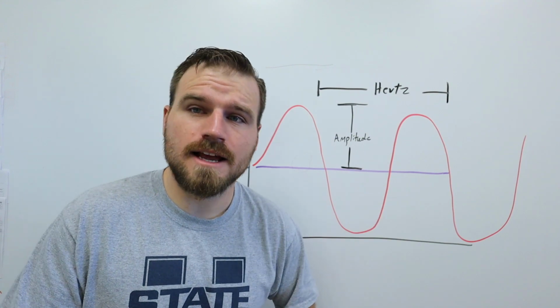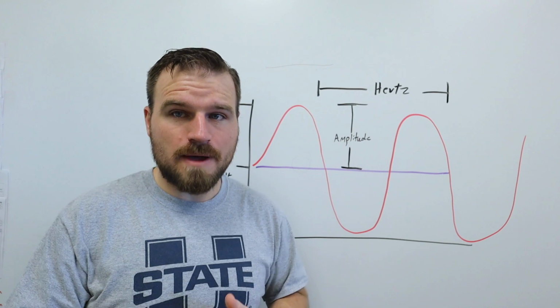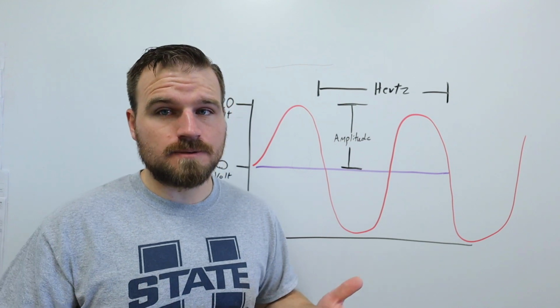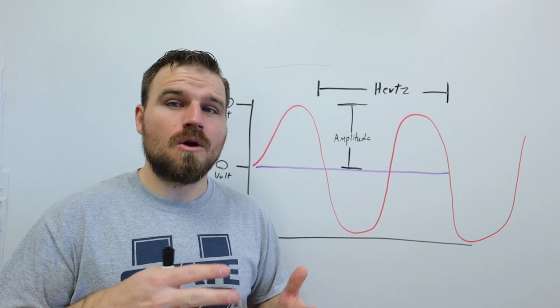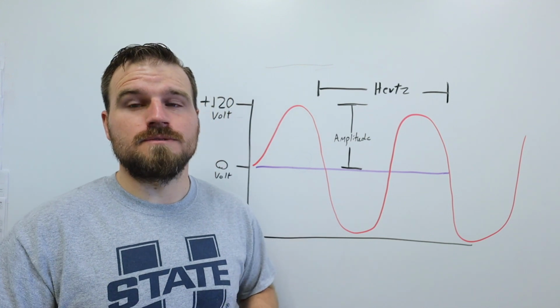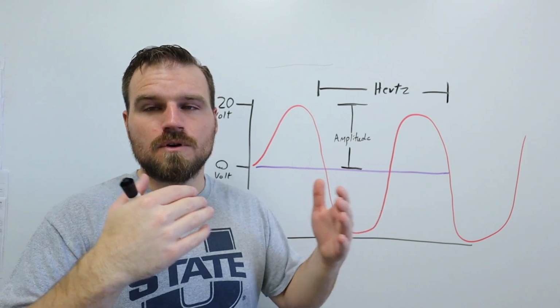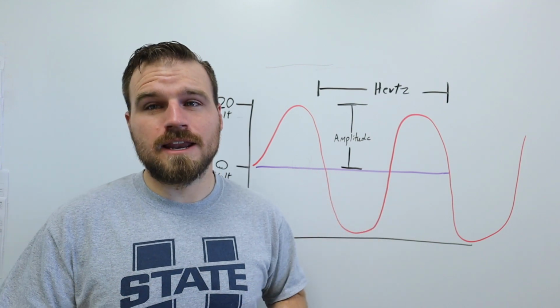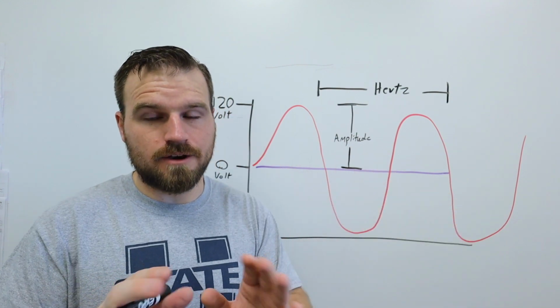Another thing is it can actually raise the voltage quite high and then bring it back down using transformers. We've talked about that a little bit, and we're going to talk about that a little bit more. But transformers are only used with AC voltage because they're actually creating that alternating voltage back and forth, which causes those magnetic flux lines to induce voltage in a transformer. Talk about that a little later.